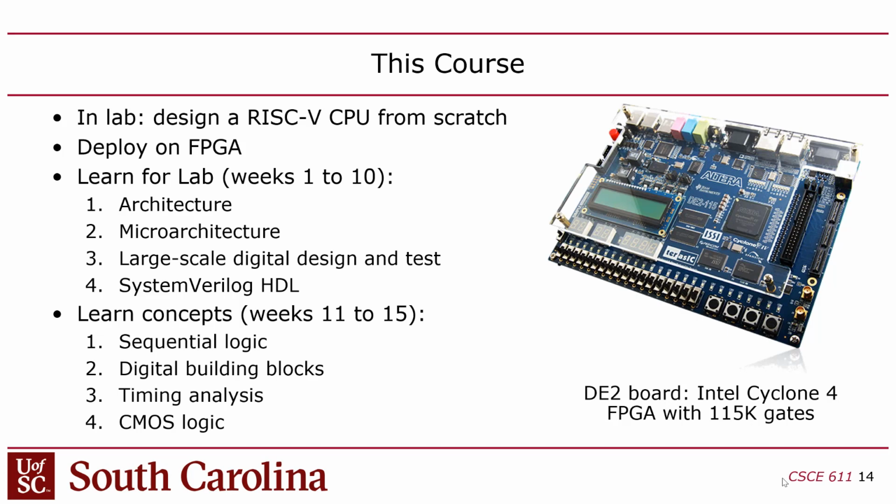So this board has switches and buttons and 7-segment LEDs, an LCD display. It has Ethernet and serial port and parallel port and GPIO and high-speed mezzanine connector and 3 USB ports and infrared port. It's got a bunch of stuff on it. It has 4 different memories: DRAM, SRAM, soldered flash, and an SD card flash. And it's got SMA for high-speed clocking, and what else? I guess that's about it. Oh, it has an audio chipset. It has a TV decoder chipset. So it has A to Ds, D to As, VGA out, which we probably won't get to.